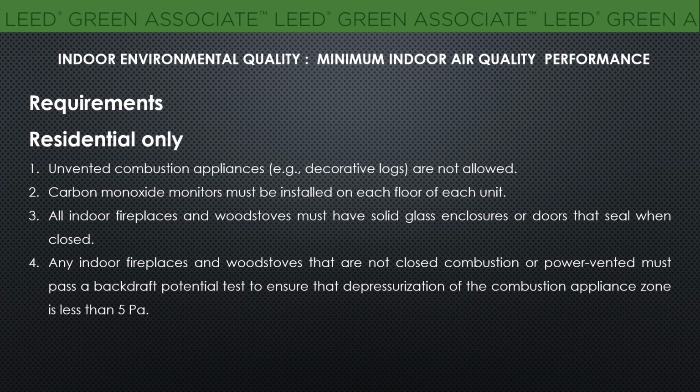And next, any indoor fireplaces and wood stoves that are not closed combustion or power vented must pass a backdraft potential test to ensure that depressurization of the combustion appliance zone is less than 5 Pa.